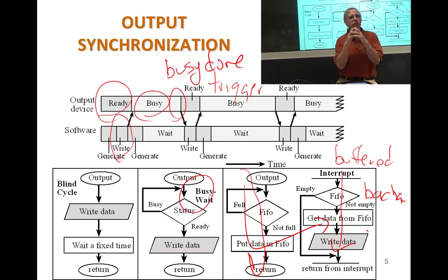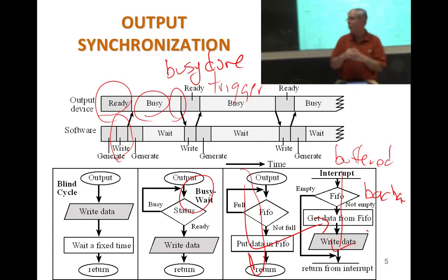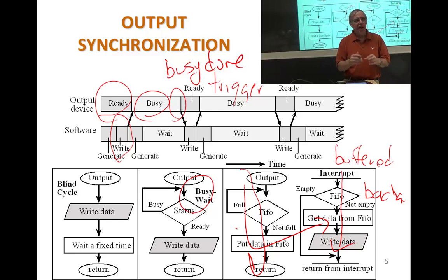So whenever we share information between multiple threads, we must use globals. Now I will say the right way to do it is a private global, a global which is private to this FIFO routine, and then provide some public functions like put FIFO, get FIFO, initialize FIFO, that the other programs use to get at those globals. And that way your access to the globals is done in an appropriate way. We're going to do globals in this class.